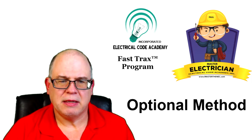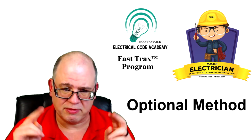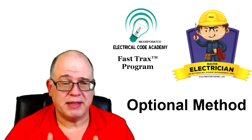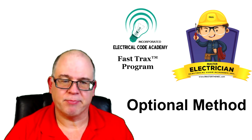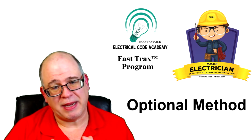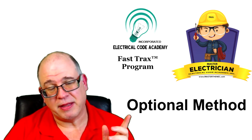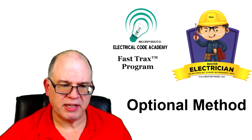So we're going to talk about the optional method today to get our ungrounded conductors, our hots, if you will. You're not going to utilize the optional method in order to size a neutral. You're going to have to go use the standard method to do that. Okay, so go watch that in the standard method. And again, it's going to apply here. You just do the optional method and do the standard method to determine what the neutral is. Okay. All right, so let's get into it.